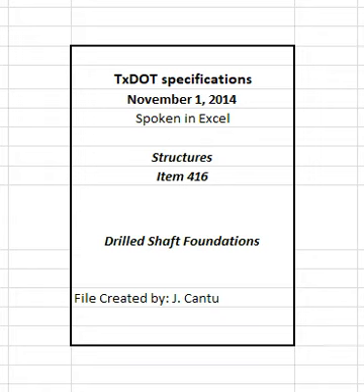Time of concrete placement is described in Section 416.3.6, Concrete, and Section 416.3.7, Additional requirements for slurry displacement or underwater concrete placement methods. Note the temperature of the concrete mix at the beginning of the slump loss test. Place the concrete if its temperature at the time of placement into the drilled shaft is no more than 10 degrees Fahrenheit higher than the slump loss test temperature.